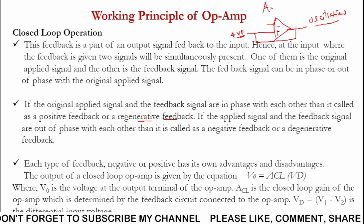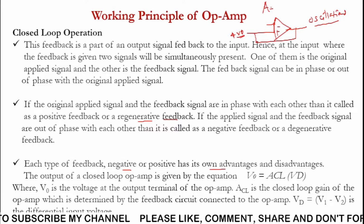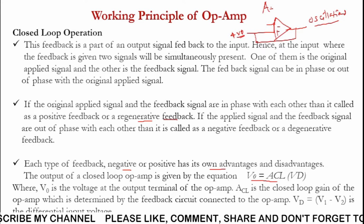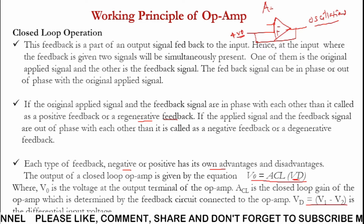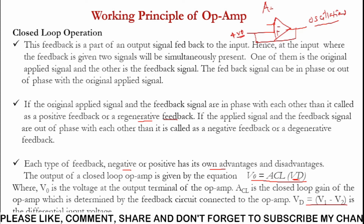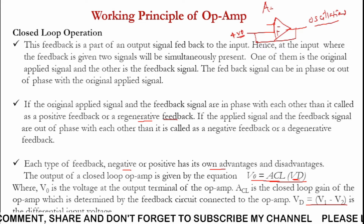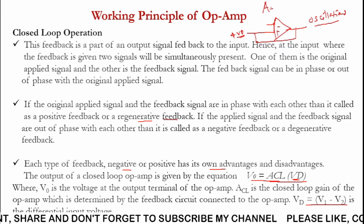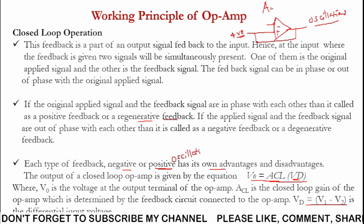So look at the gain. In this case, VO, that is the output voltage, is equal to ACL into VD. ACL is the closed loop gain. VD is the differential voltage, that is equal to V1 minus V2, where V1 is at the non-inverting and V2 is at the inverting input. ACL, the closed loop gain, will be reduced in case of closed loop operation. How it will be, we are going to see.